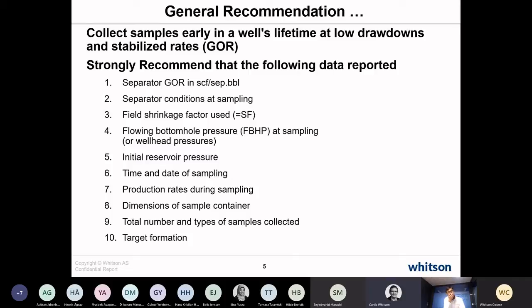Whether it's depletion, like Bilal said, or gas injection, that really is going to reflect the spread and composition of the zi that you're basically flashing at whatever conditions, P and T. So that composition dependence of the K values needs to be hammered out in the equation of state development. And to do that, you need PVT with varying composition.